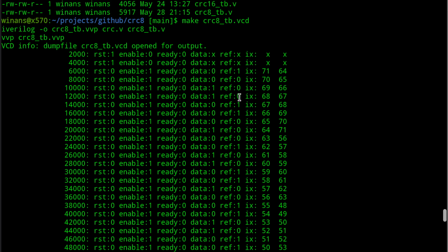If you receive them in this order, which is reflected, you want to, again, process them in the native order that they arrive, so that if you have adjacent bits that are all corrupted in a row, which is the nature of a magnetic medium or a serial cable or something like that, you want to feed them into the CRC logic in the native arrival order. Otherwise, you're not going to get the optimal value out of the CRC. You can get false positives. And this is one way you can make it suck more than it needs to. So don't do that, okay?